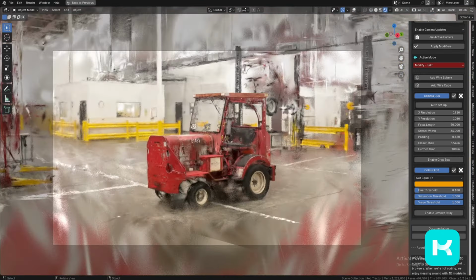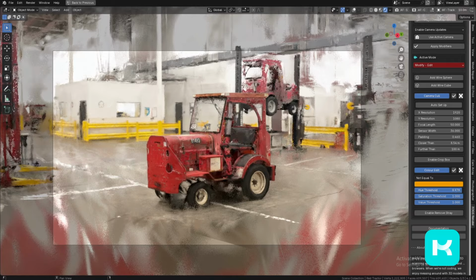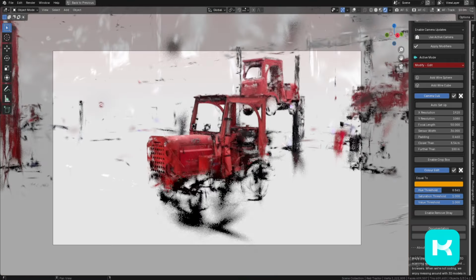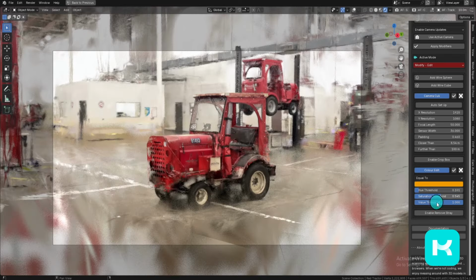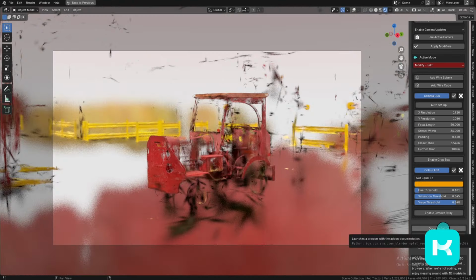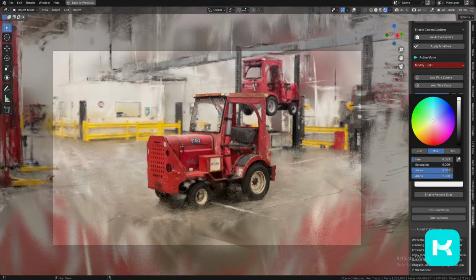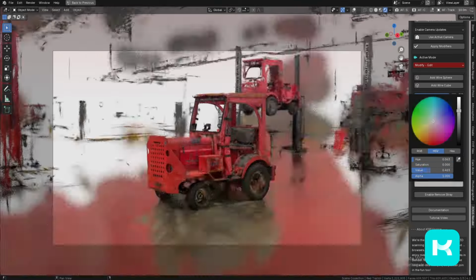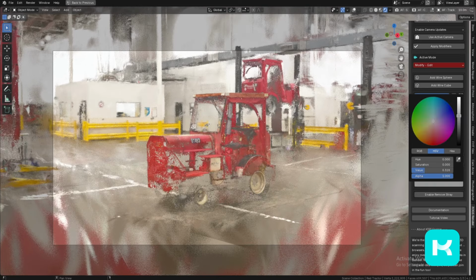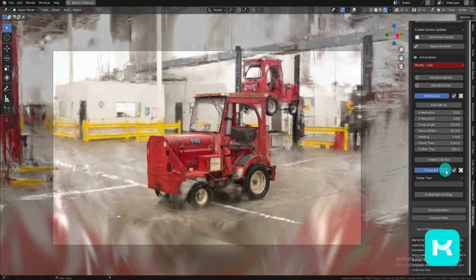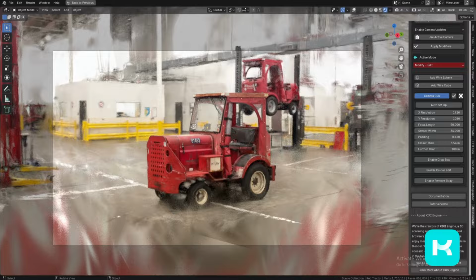Color edit allows you to remove faces according to their color. A color selection and a removal method can be set. Faces can be removed if their color is equal to, not equal to, darker than, or brighter than the selection color. The selection can be controlled with hue, saturation, and value thresholds. However, due to a Blender limitation, red values may be very difficult to select.